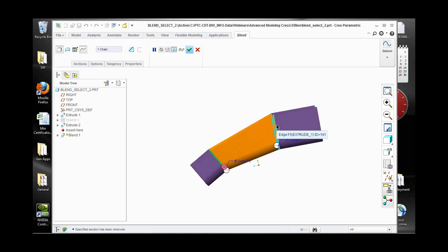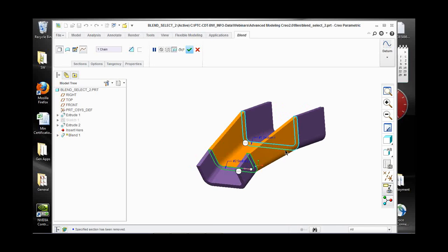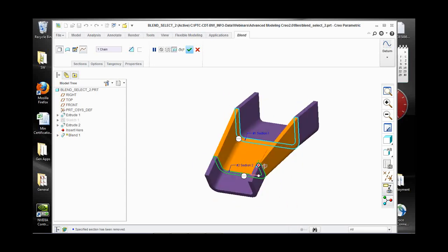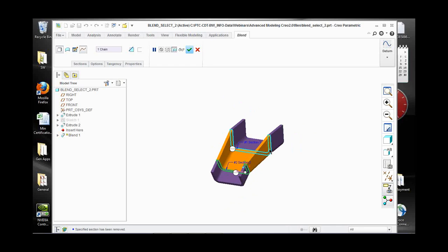But when you created a parallel blend, you had to actually create parallel sketches. Well, in this case, now I can blend between non-parallel objects because I can just select them, and you can see the blend that it does, okay? So there's my blending now between selected objects, okay? Yes, they can be parallel, but they do not have to be.